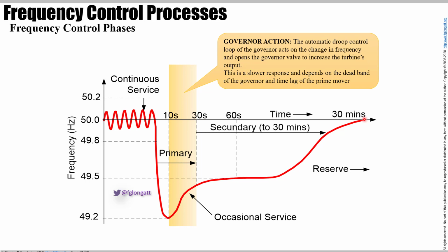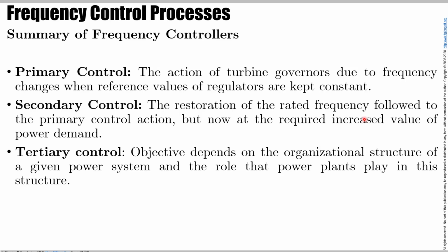To do that, basically what the AGC is doing is changing the reference, the active power reference for the generators, and increasing the mechanical power in order to increase the active power, and the machines accelerate and start to come back to the rated frequency, okay? That is basically a very short and basic introduction about AGC. However, if you are watching this video, it's because you know what an AGC is, and you just want to know about the model inside PowerFactory, okay?